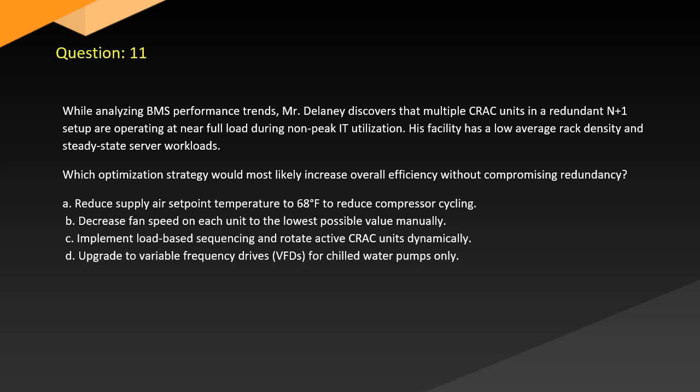A. Reduce supply air set point temperature to 68 degrees to reduce compressor cycling. B. Decrease fan speed on each unit to the lowest possible value manually. C. Implement load-based sequencing and rotate active CRAC units dynamically. D. Upgrade to variable frequency drives, VFDs, for chilled water pumps only.